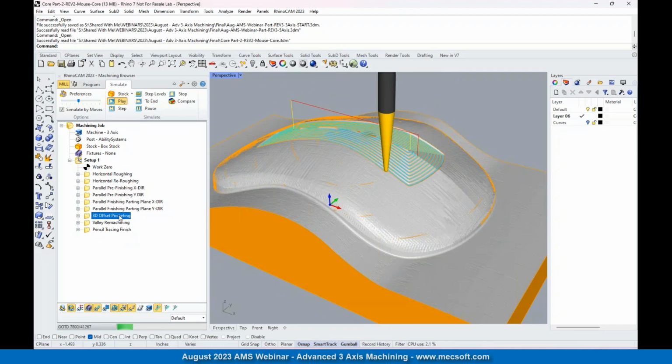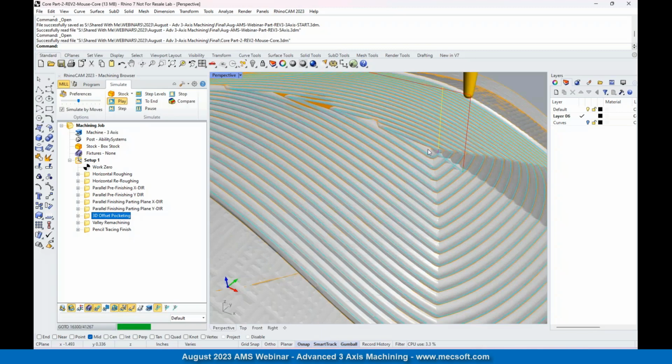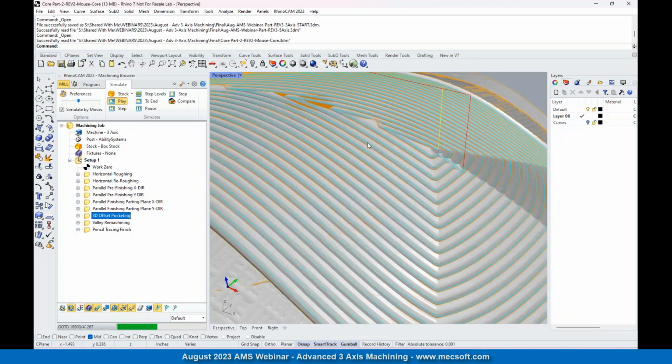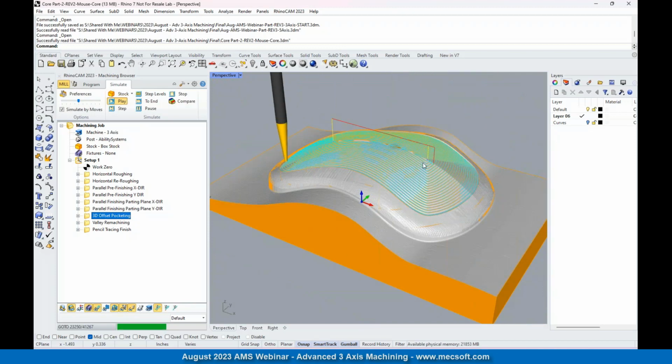This path works good. Use the largest ball that you can, okay? Only because of the way the toolpath wraps on there, you may see some excess areas right here. So with a larger ball, you won't see those. With a real small ball, you want a smaller step over, so you make sure you get rid of these or get a smooth surface right across the center there. Okay, so let's pause that.